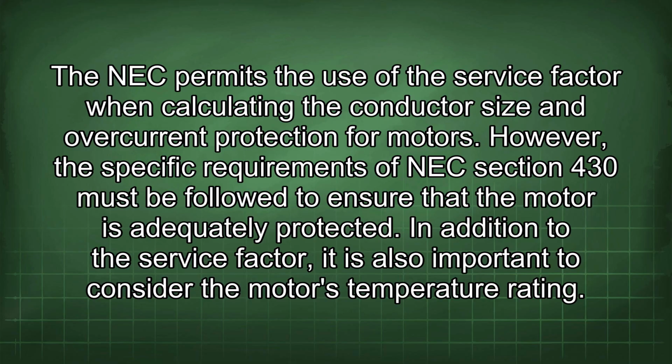The NEC permits the use of the service factor when calculating the conductor size and overcurrent protection for motors. However, the specific requirements of NEC section 430 must be followed to ensure that the motor is adequately protected.